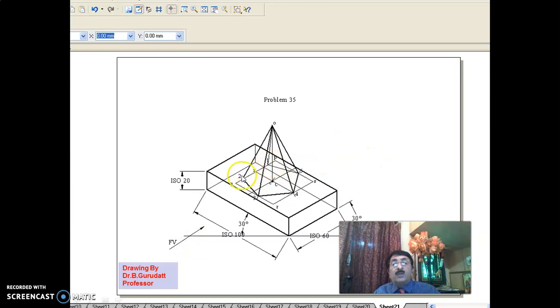In that way, 1 to 2 will be to the left of the observer and it will be perpendicular to VP. In that way, the condition is met. Okay. Once you have done this, for the top solid's visibility, the top surface is any point. Then go along the outer boundary. Then the edges on the left surface and right surface, you darken them.